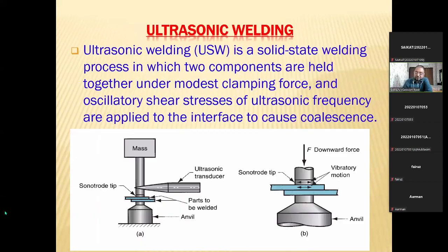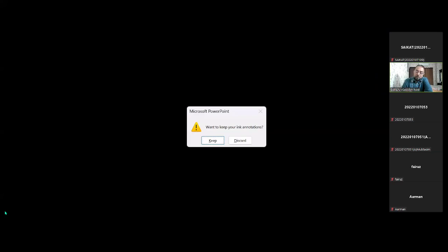So you remember, ultrasonic welding means here one metal is placed between the two tips, then we shall use a mass here and give a vibration, which is ultrasonic vibration. That means this transducer will give the ultrasonic vibration. This vibration will be transferred to the joint, and as a result the molecules will come in contact and unite. As they unite, the metals will be joined. Okay, that's all we want to tell you. And that is the last topic we are going to study today.